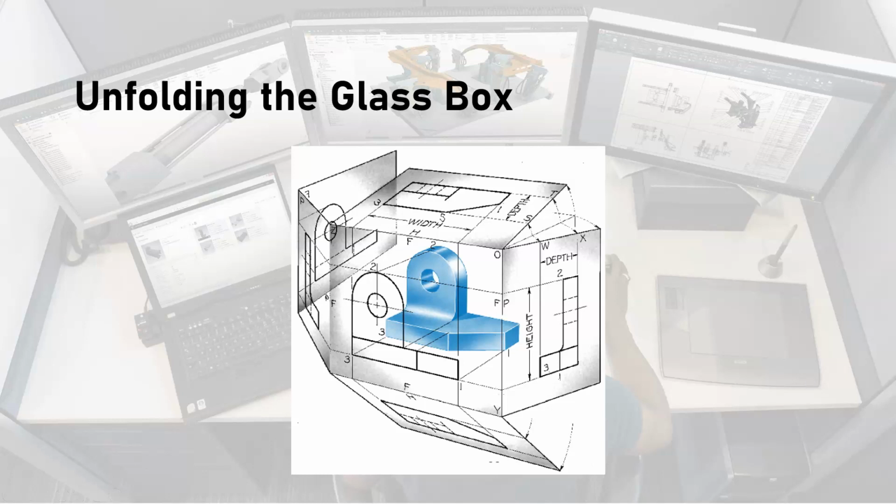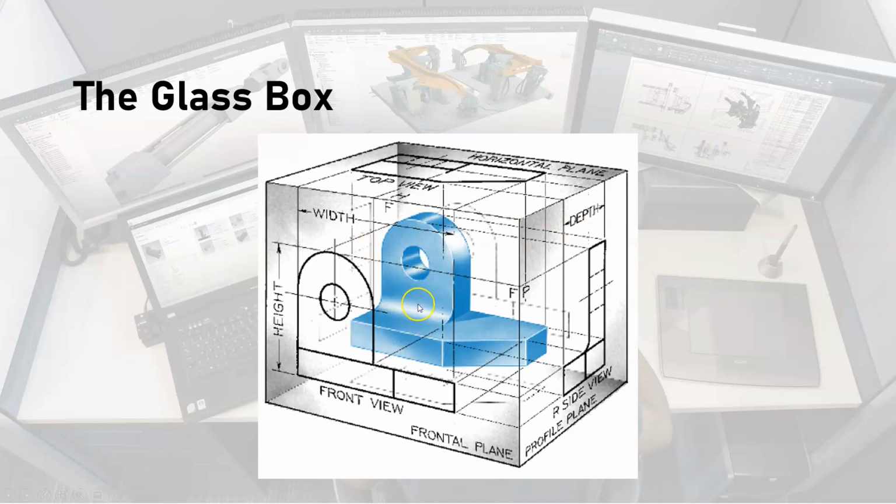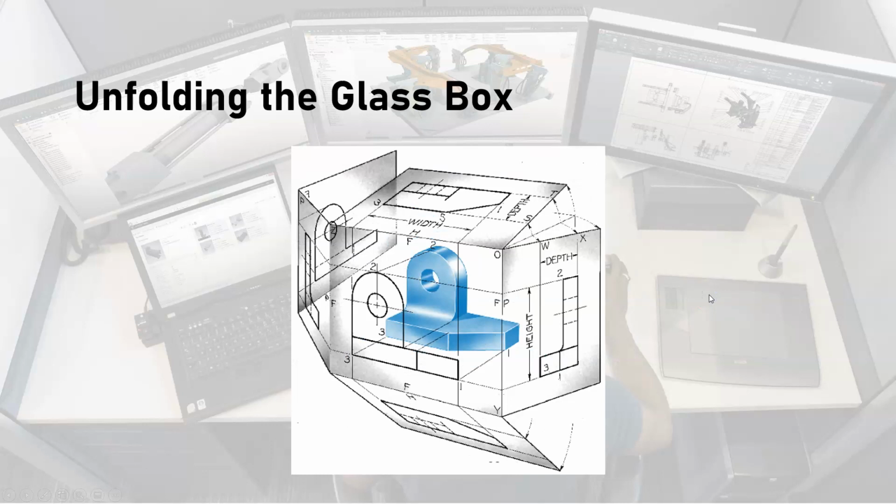Then what do we do with the glass box? Well, we unfold it. All right, and this is how we get our alignment of our orthographic views, which is a very, very important, very critical thing, the alignment of the views. So it's not just sufficient to have the views like this in a glass box, because the glass box is 3-dimensional. That doesn't help us. We need to get it into a 2-dimensional surface. And so we unfold the glass box.